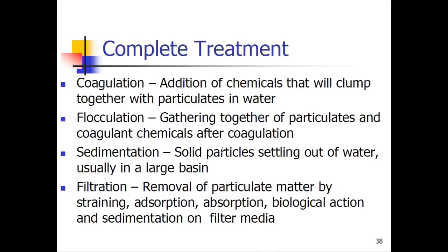Complete treatment. What are we looking at? Complete treatment is coagulation, which is the addition of chemicals that will clump together with particulates in the water. Flocculation, which is gathering together particulates and coagulant chemicals after coagulation. The sedimentation process then is solid particles settling out of the water, usually in a large basin, and then we do filtration after that, which is the removal of particulate matter by straining, adsorption, absorption, biological action, and sedimentation on the filter media. And obviously then we still have to disinfect.